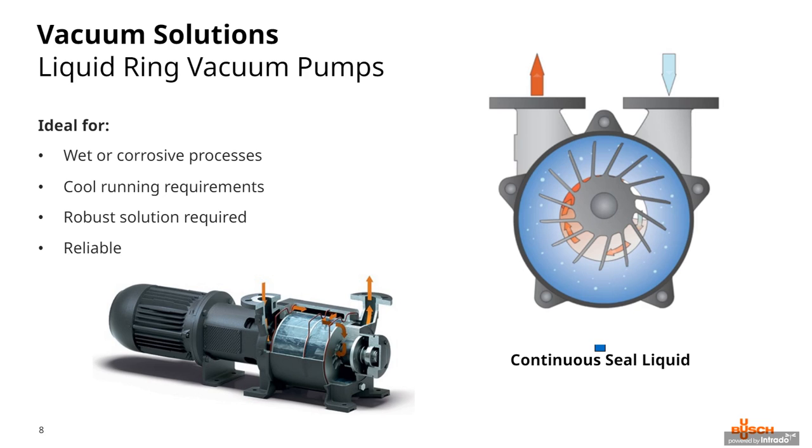The liquid ring seals the individual spaces down to the cylinder. Therefore, it is sometimes referred to as the sealing fluid instead of the operating fluid. The liquid ring seals the gas chambers, cools the incoming gas, absorbs the heat of the compression and the condensation, removes impurities, and cools and lubricates the shaft seal. These pumps are ideal for wet and corrosive processes.